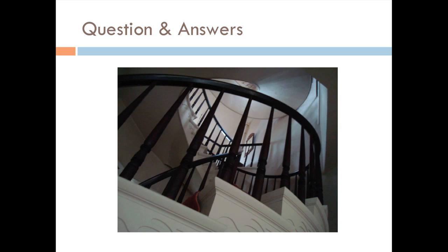And I guess what I'm asking is, if you put the hydraulic lime up there and it's more porous, is it going to resist the wind-driven water from coming in? It will, because if it can be used in marine environments and it holds up in a durable fashion for many, many years in the ocean, I don't see why it wouldn't work on a stone farmhouse.